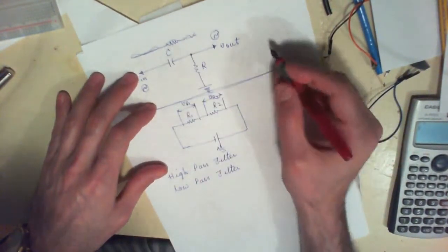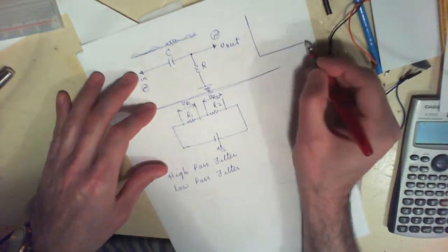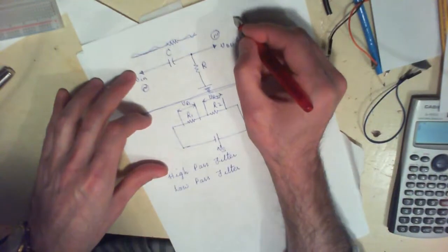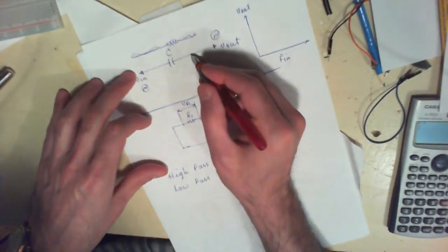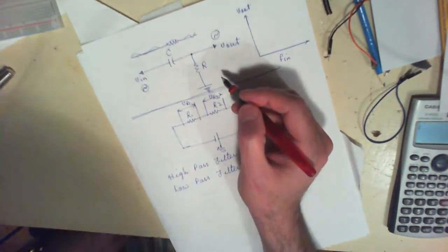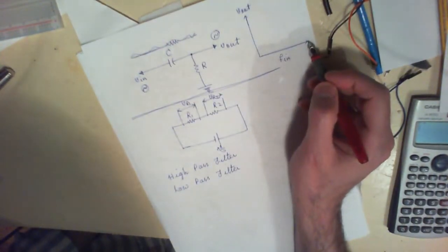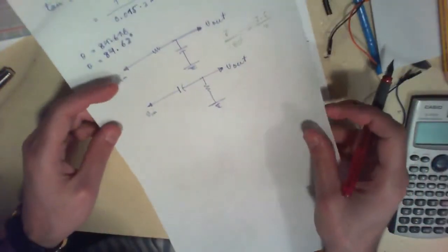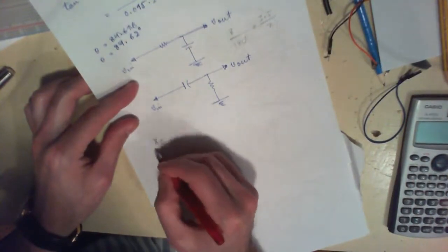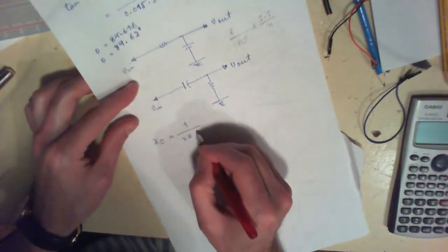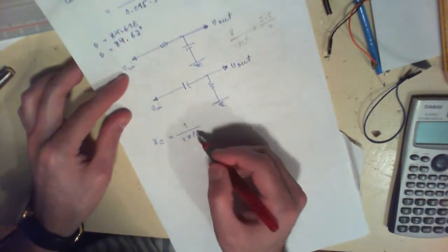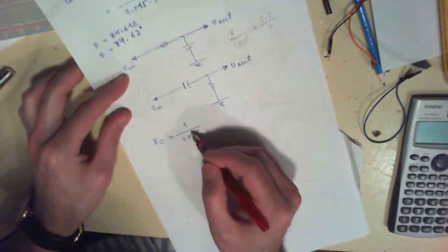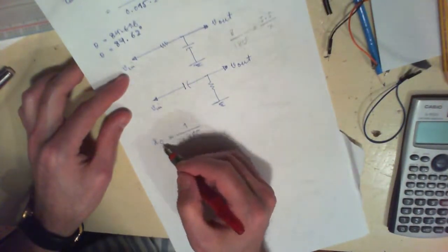So if you have the graph of the input frequency of this circuit versus this V of out, which by the way is also the voltage across this resistor, what happens is that as you increase your frequency, the reactance of this capacitor is going to decrease, because you know that X of C, the reactance of the capacitor, is 1 over 2 pi f C. Since f is in the denominator, the more you increase your frequency, the lower the value of this reactance is going to be.